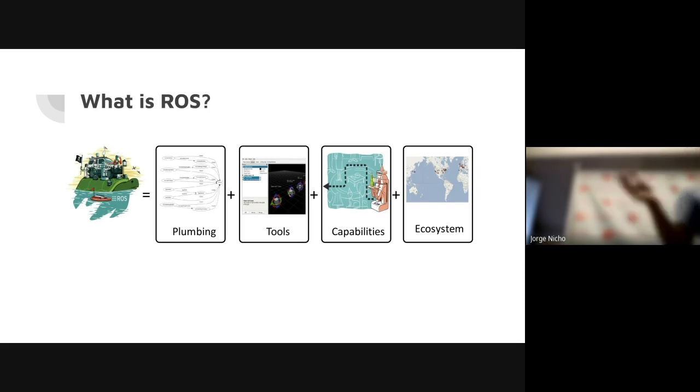On top of that, you have capabilities. For instance, if you want to do motion planning for a robot after you observe an object you want to pick up, rather than writing the motion planning algorithm, you can look to see if there are capabilities that already provide that. You can use some out of the box. For motion planning, there's MoveIt.